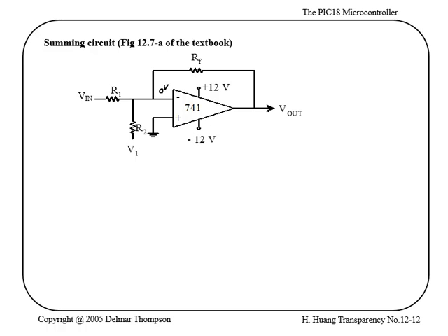And if you look at your V out, essentially whatever currents that you have, if this is current I, then your V out is going to be minus I times RF. Alright, this is ground, this is your positive voltage, so your V out is going to be minus I RF.